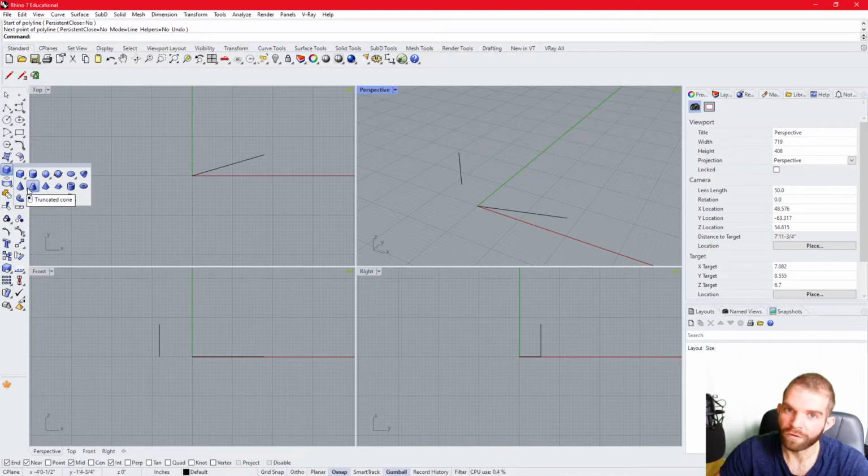Solids are essentially surfaces that are closed. They're not 2D surfaces, they're 3D objects. A solid technically has no openings. You can have many 2D surfaces joined together, but if there's a missing 2D surface, that would not allow that geometry to be solid. This is more on topology. We'll talk more about that later in a different video on topologies of geometry.